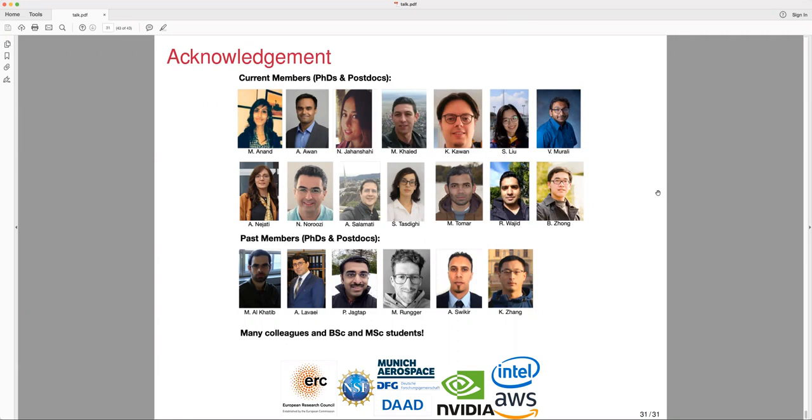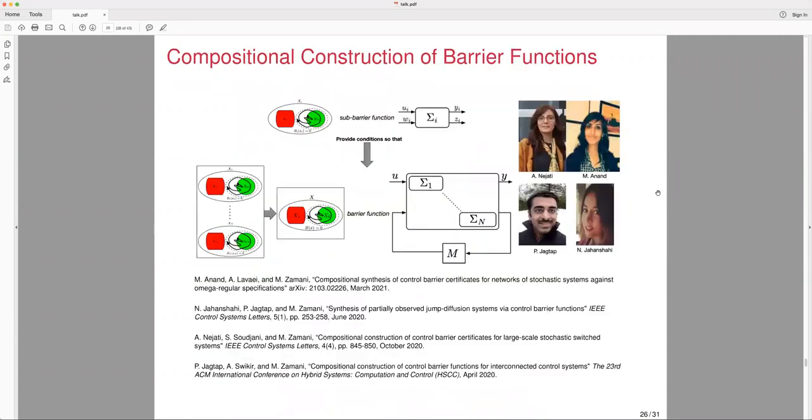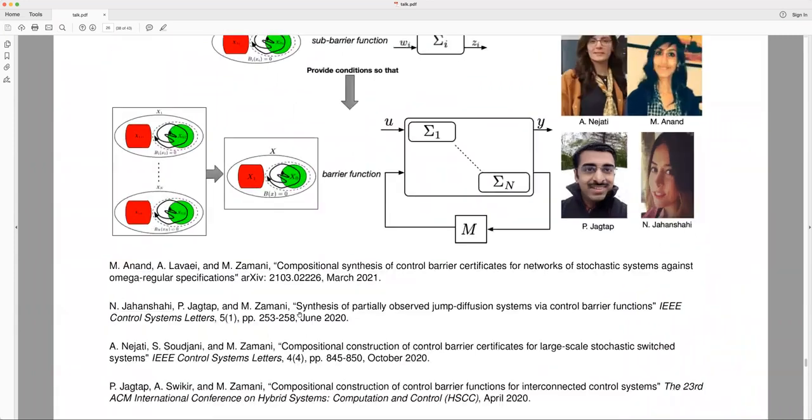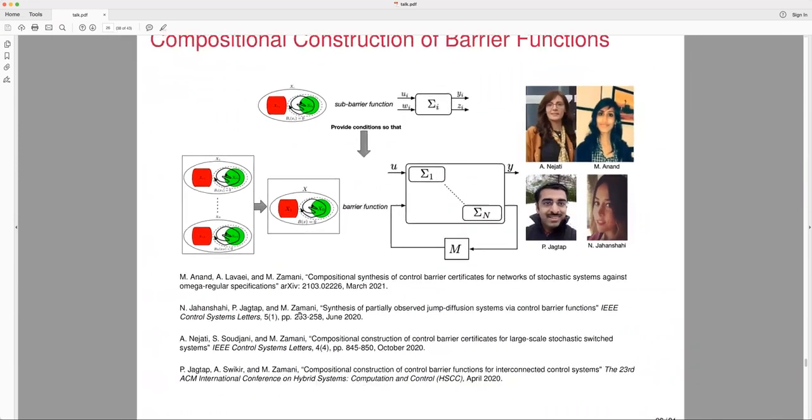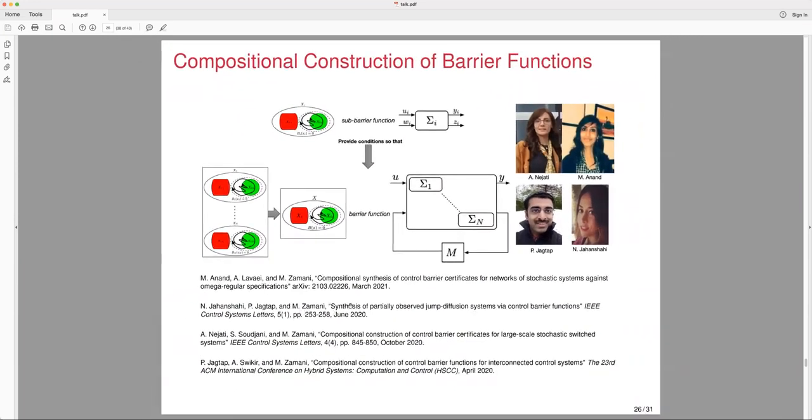I see where you're going with this, but one thing I wanted to ask you about was, you assume that there is sensing taking place and you're able to construct the state of the system. From everything I saw, you're using full state feedback. So how do you talk about using camera and LiDAR inputs to reliably get to the state of the system, which is often a big problem that breaks a lot of these guarantees? Can you talk about that?